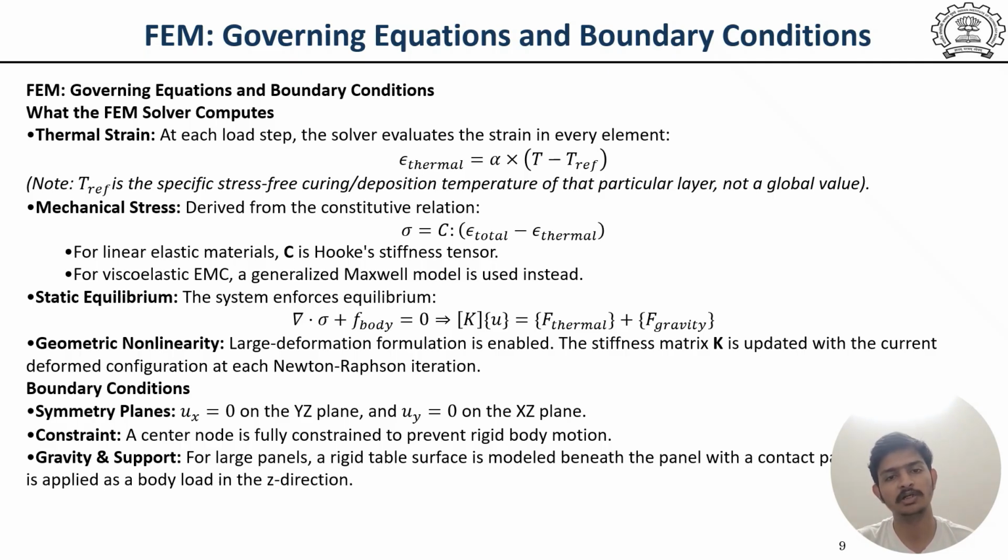Importantly, we enable geometric nonlinearity. When a large panel warps, its structural stiffness actually shifts. The solver recalculates and updates the stiffness matrix every single iteration to reflect the newly warped shape.